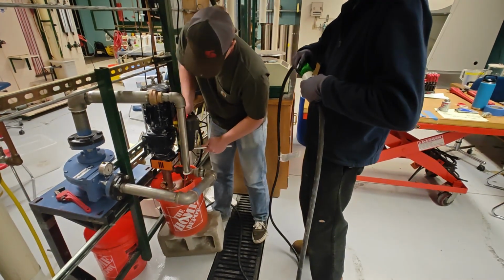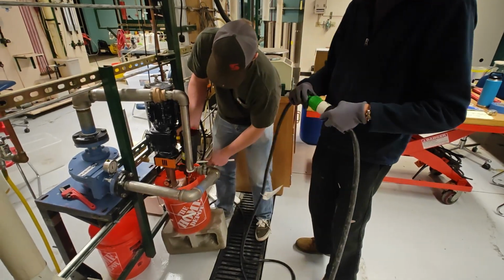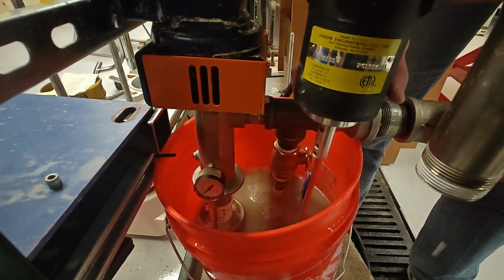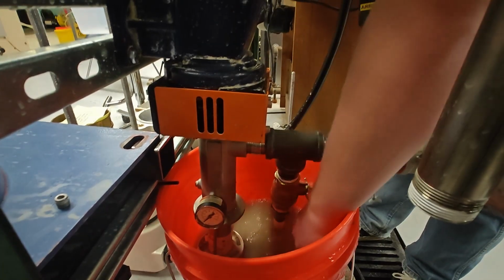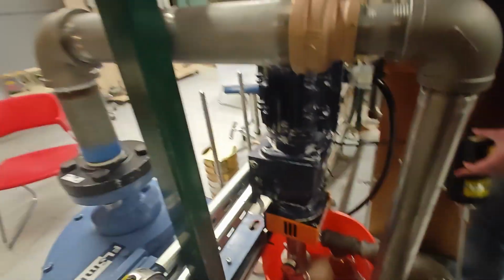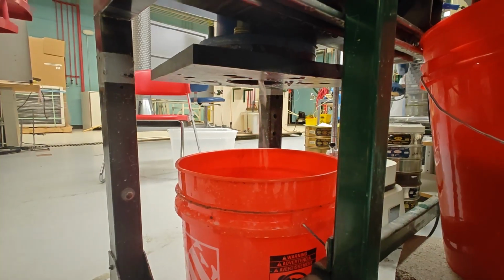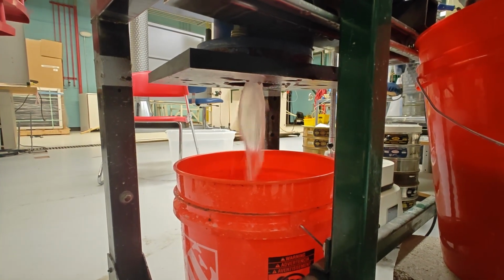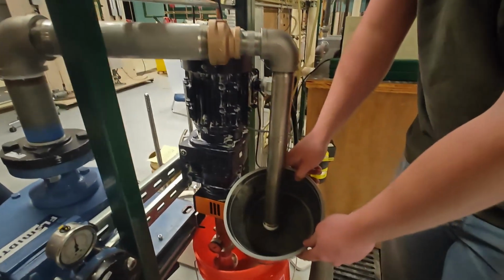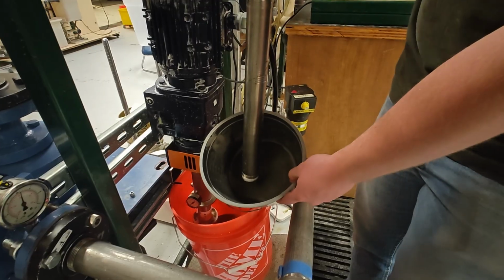After agitating the slurry, the pump is powered and bypass flow is used to further circulate and stir the tank. Once the solids are fully fluidized, the bypass valve is closed, allowing flow to enter the system. The outlet stream provides an indication of system performance by monitoring the flow pattern. A ropey, semi-spray appearance, as seen here, is optimal and indicates the solids are freely exiting. The overflow consists primarily of the carrier liquid, with only a small amount of fine particles present.